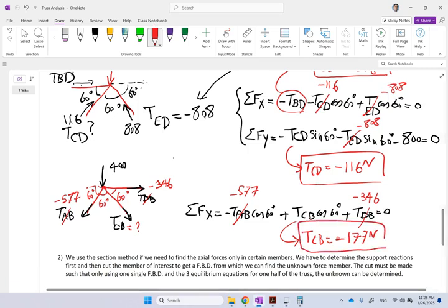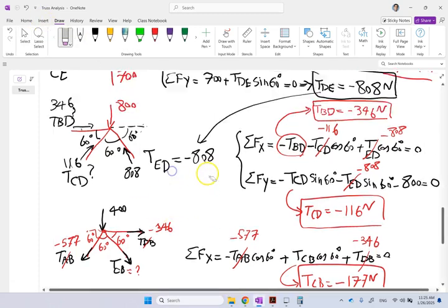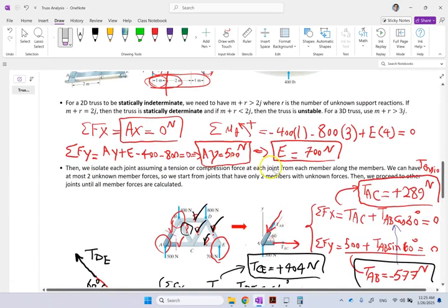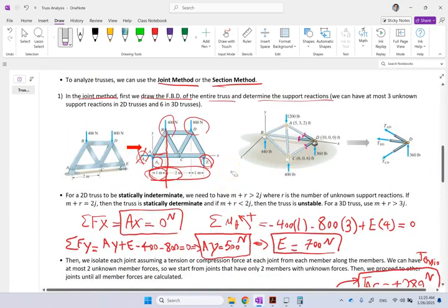Done. Now I have all truss members, all the forces are calculated, therefore my truss analysis is over because I have all the reactions and all the forces. And I could do that because it was statically determinate. Now you clearly can see that this is a time-consuming process because you have to find so many unknown reactions, right? And forces, M plus R of them.